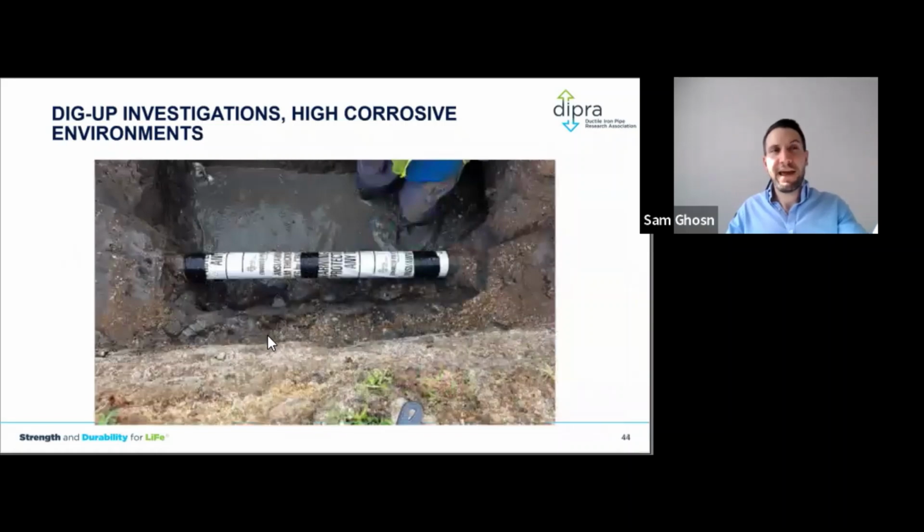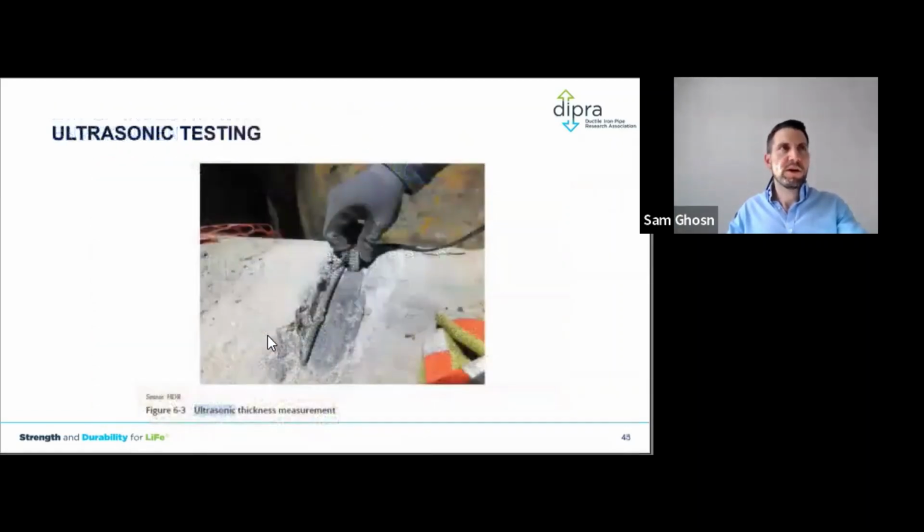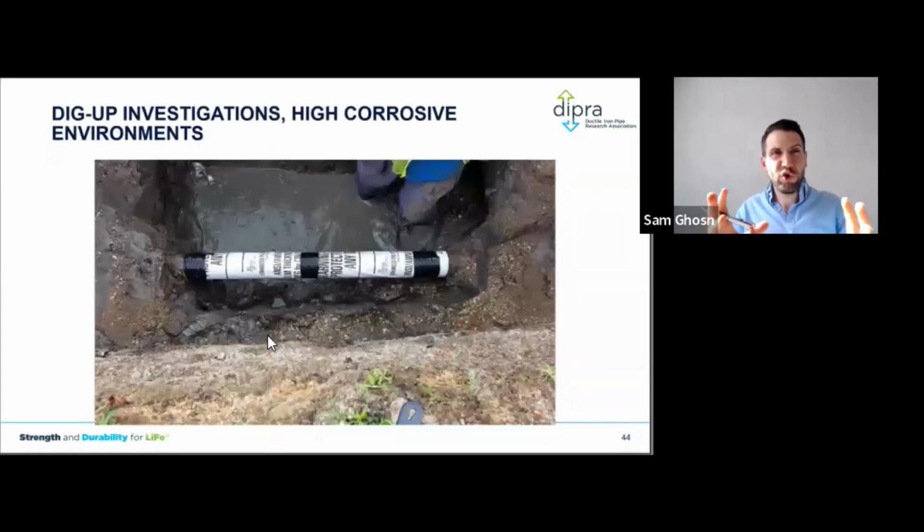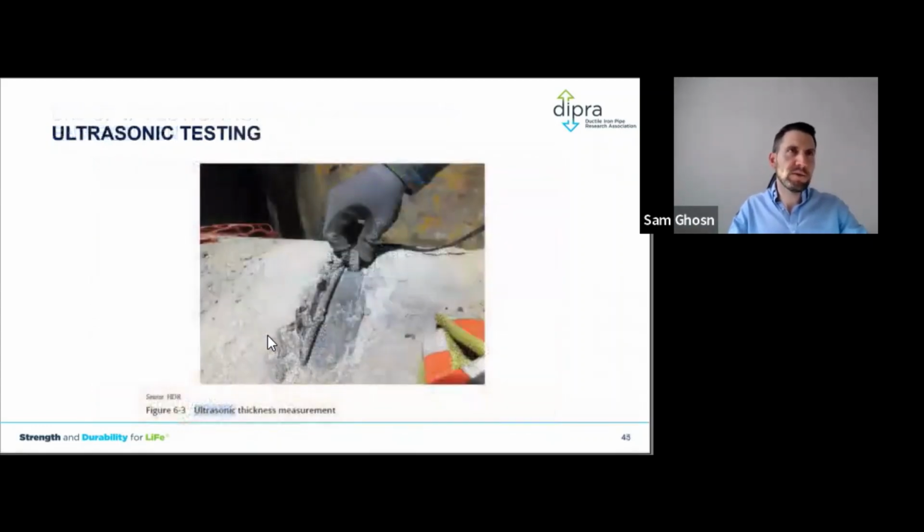So last step in every dig up, folks, when you do a condition assessment, is you access that pipe, you look at it, please put back the polyethylene encasement if the pipe is wrapped, so you could extend the longevity of that polyethylene encasement. Okay, because polyethylene encasement is a great tool, very effective, very economical. However, the installation is very critical as well. If you have inspectors in your cities, you want to make sure that they understand inspection, and I'm happy to help with any of that training as well. Understanding inspection and proper installation is key for the success of polyethylene encasement.